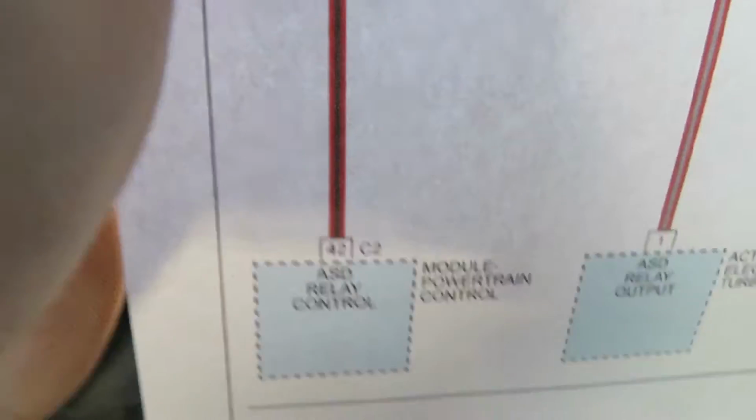That is the only connector in there other than the ECM connector. But in my experience, it's hardly ever an ECM connector, usually something underneath the TIPM. So once you get to the bottom of it and find the blue connector, which is C130, undo that and just look for pins that are corroded or broken off or bent or anything like that.